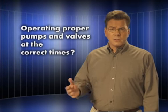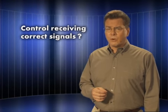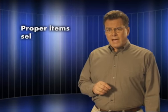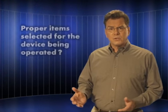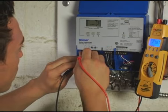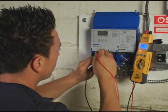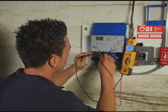Isolate the problem between the control and the system. Now that the sequence of operation is known and the system is sketched, is the control operating the proper pumps and valves at the correct times? Is the control receiving the correct signals from the system as to when it should be operating? Are the proper items selected in the menus of the control for the device that is to be operated? Test all contacts, voltages, sensors, and wiring to ensure that the control is receiving adequate voltage to the power terminals and the demand terminals as noted in the technical data.